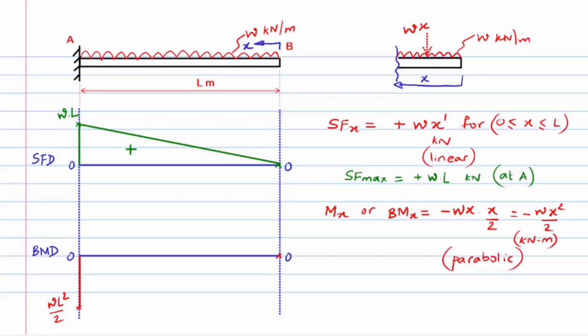It now remains to see if the parabolic curve to be drawn between these two positions is a maxima curve or a minima curve. For this, we check the sign of the double derivative of the bending moment equation with respect to the variable x. We find that the double derivative is negative in sign, meaning that the locus is a maxima curve. We hence draw this approximately between the two positions and name the curve as parabolic.